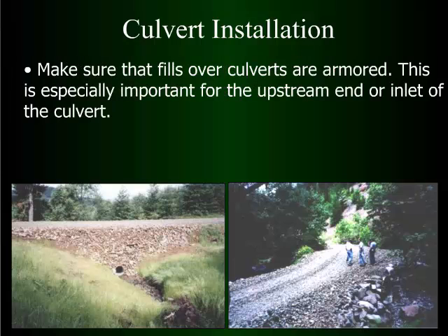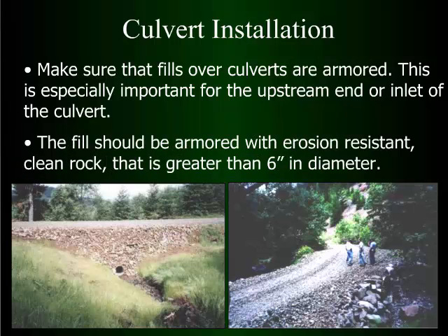Good culvert installation. They've armored the outside a little bit. The pipe actually sticks out through the rock. Good armor on the pipe inlet there. Minimize erosion problems. Yeah, that's rock bigger than 6. I don't know if most people are going to be willing to import rock, but if you have rock handy, it's always good to sort it out a little bit and save it once you get the pipe installed. Save the bigger pieces to put around the outside, the biggest ones closest to the pipe.